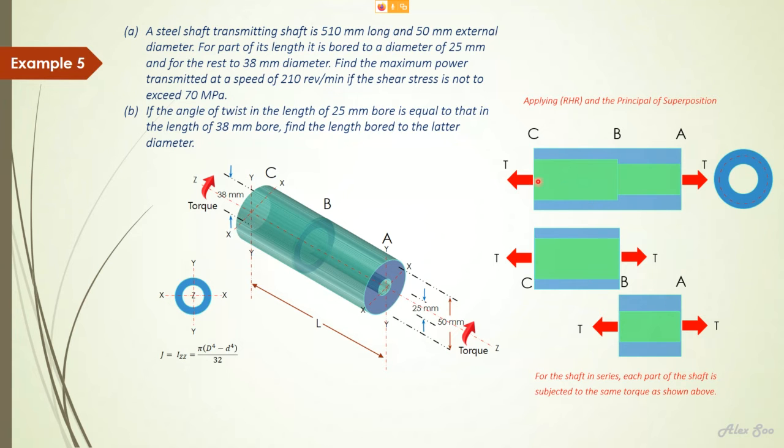So the torque here, how are you going to convert this? The torque to linear like that. You can use either your right hand or your left hand for both, flipping over the shaft. It will show you the direction of the rotation of the shaft. So when you refer to section B here, T is equal to 0. So we take T here from section C for the equilibrium of the section. If this is T, this should be T.